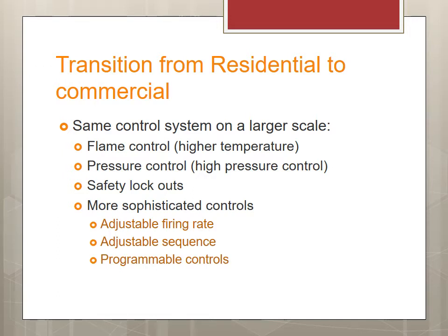We need more pressure control because we're no longer working with 2 psi or 15 psi. This is going to be a lot of pressure, and mostly for power plants, so it's really more sensitive to pressure and how we operate. We also control the flow operation with low and high pressure. We need a lot of safety lockouts, meaning that if anything goes wrong, we need the whole thing shut down. Again, we are working with a large amount of fuel. So again, we need more sophisticated controls.